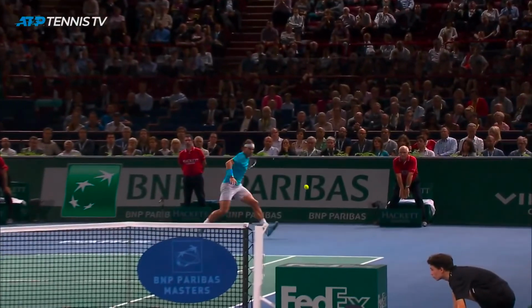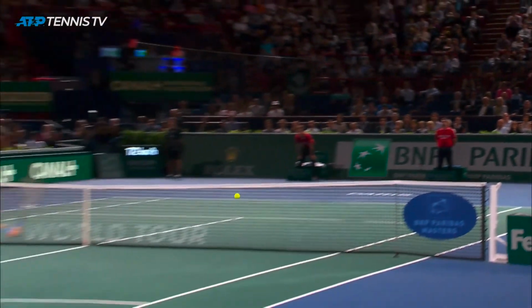Okay, now the tennis ball is a little bit different. Tennis balls bend because of spin. So a ball hit with topspin curves downward, and a ball hit with underspin travels in a much flatter trajectory. Now this matches the Magnus effect, which is experienced by a circular cylinder, and that's accounted for by the Bernoulli equation. And I show that explanation of this in the undergraduate level fluid mechanics course. So again, there's a link to that at the top right corner of this video.